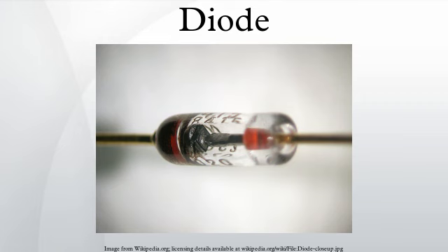For silicon diodes, the built-in potential is approximately 0.7 V. Thus, if an external current passes through the diode, the voltage across the diode increases logarithmically with the current, such that the P-doped region is positive with respect to the N-doped region, and the diode is said to be turned on as it has a forward bias. The diode is commonly said to have a forward threshold voltage, which it conducts above and is cut off below. However, this is only an approximation, as the forward characteristic is, according to the Shockley equation, absolutely smooth.